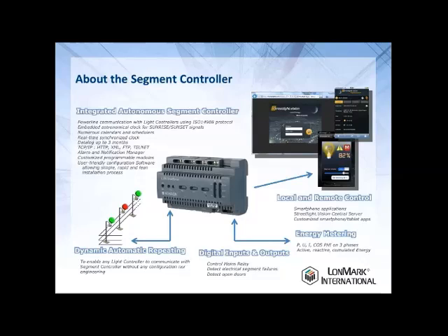locally control the cabinet. But even more, it provides all the power line communication with a standardized protocol to control any light point controllers that can communicate with that standardized protocol called LonWorks, and that is managed by the LonMark organization.